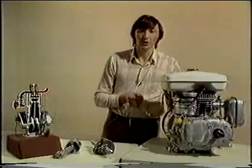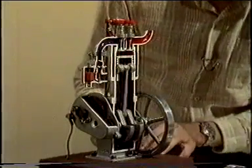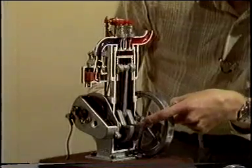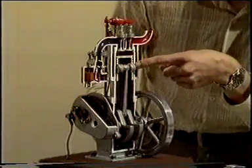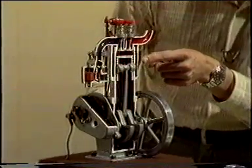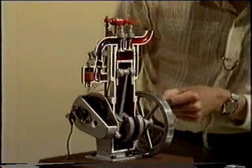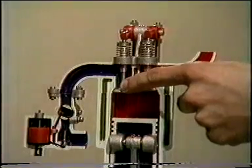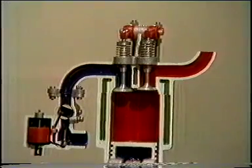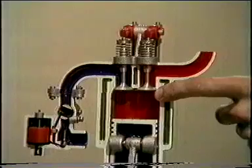And to give you some idea of what that means, I've got a cutaway model. Here we have the piston, the connecting rod, and the crankshaft. And through here, the gudgeon pin. Now the four-stroke cycle means that the piston actually makes four movements during the cycle. The first, it moves down the cylinder, the inlet valve opens, and the petrol-air mixture is drawn in. On the second stroke of the piston, this petrol-air mixture is compressed.